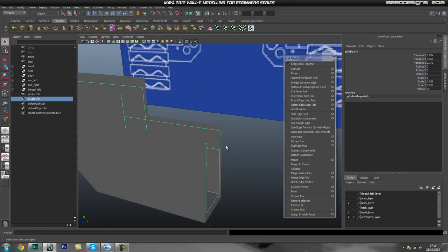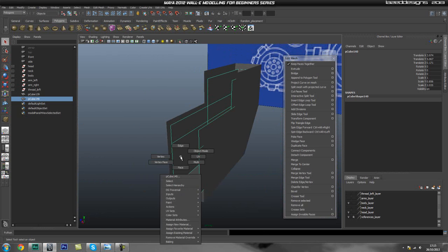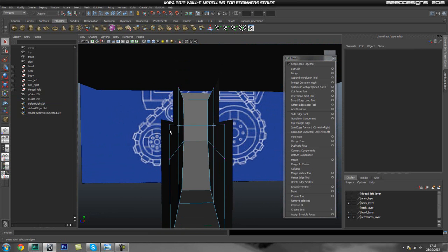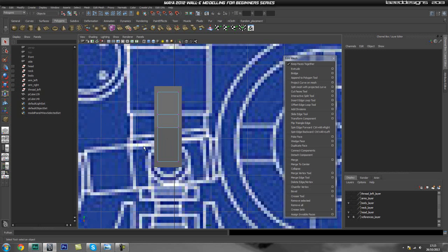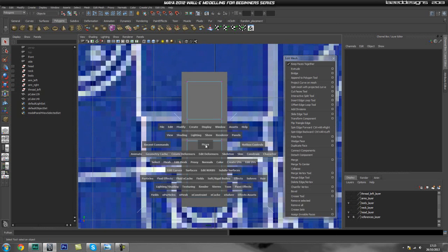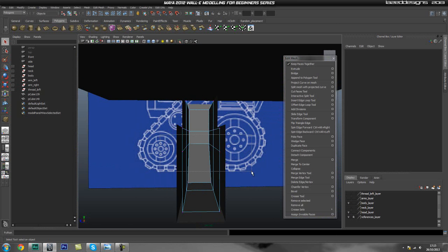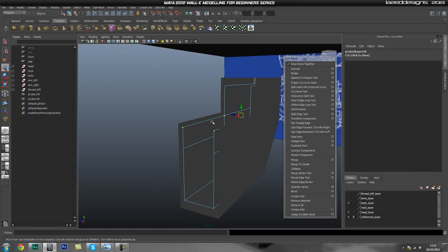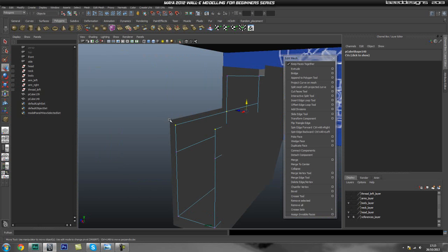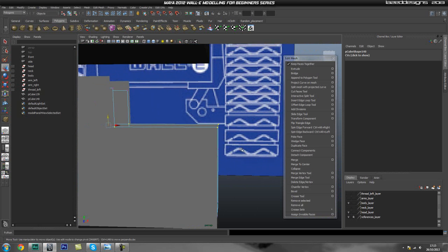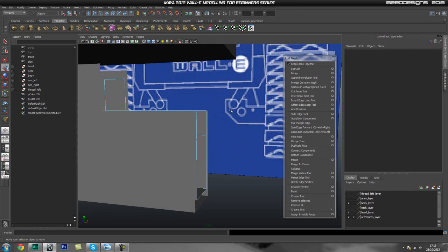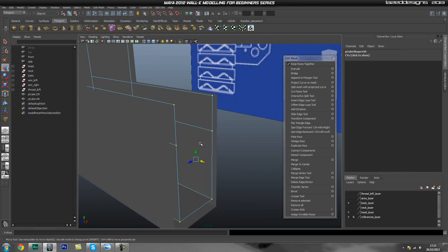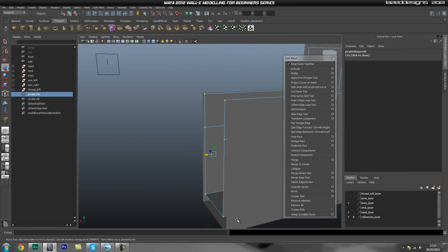Okay, so once we have this, we should be able to move around our vertices quite easily. So let's just go ahead and do that. Let's go ahead and grab in my side view, it might be the easiest. Or we can do it in perspective as well. Let's go ahead and grab all these vertices, or the one higher. Yeah, the one higher row. Select your move tool, and let's go ahead and snap it up here. And then you're going to go ahead and select all these vertices. Select that angle, and you're going to make sure that it's lining up with this.